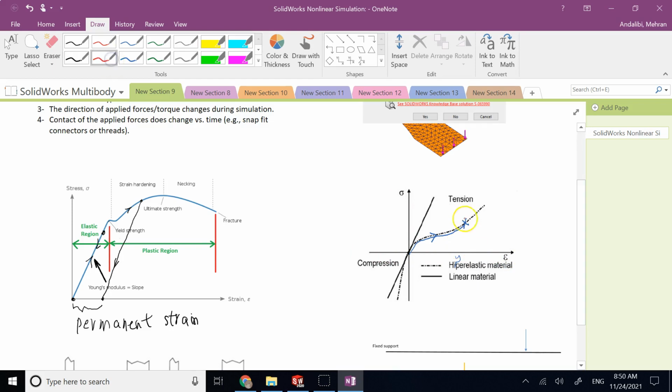As long as it is elastic, it's not going to go back parallel to any linear region because there is barely any linear region here. What it travels is something like this and still goes back to origin. And you see, the material at the end of the day has no permanent deformation. So the material is still elastic, although clearly nonlinear, because look at the relation between the stress and the strain.